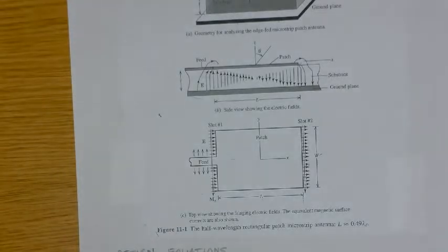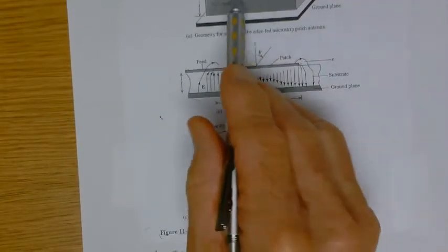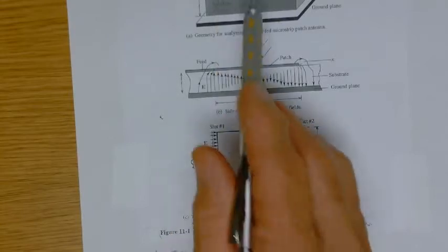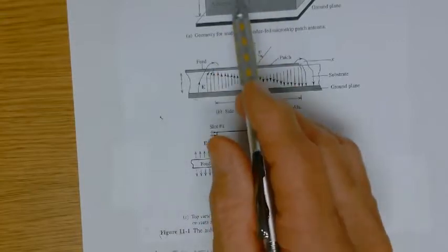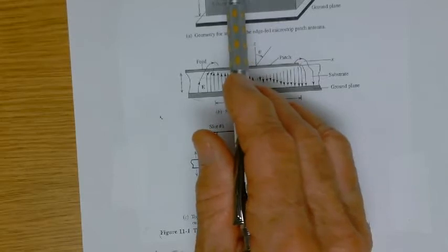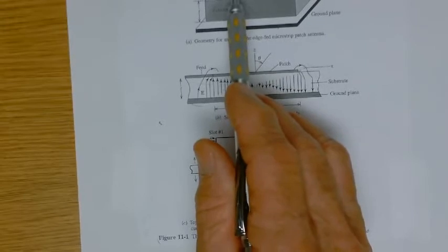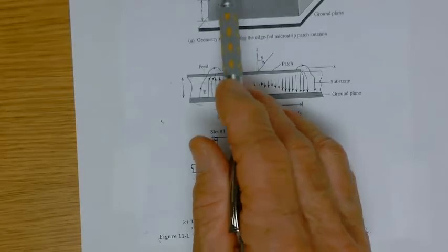Okay, so radiating edge, non-radiating edge, non-radiating edge, and then we're feeding from the left, and so the wave propagates, hits the end of the patch, and reflects back, and then the patch length lambda over 2 is such that the antenna is resonant, meaning that the voltage and current at the feed point are in phase, right?